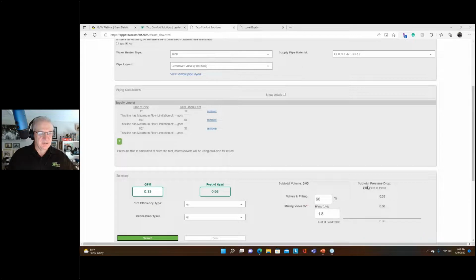It's not like the water starts out cool and gets progressively hotter as it goes through the piping system. It's cold or tepid at that point. When the pump comes on, we're evacuating that hot water line of cold or tepid water. By the time the hot water is coming in basically a slug, all right? So when the hot water reaches that valve in a slug, that's what turns the thing off. So there's very, very little, minimal, maybe that much, either warm or warmish water that gets through that valve.